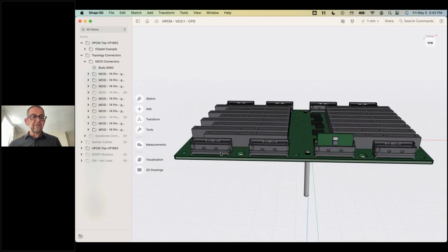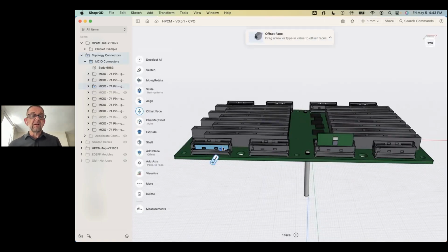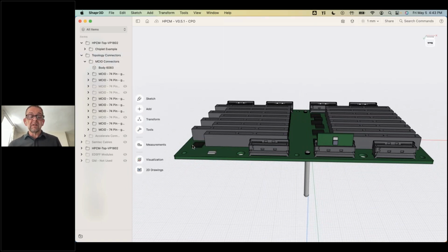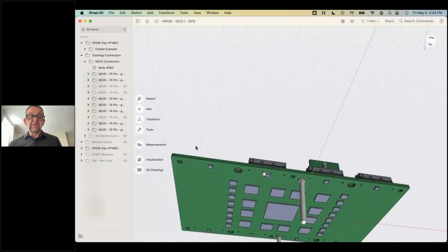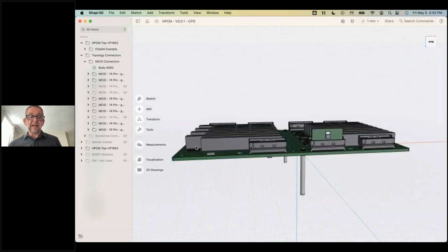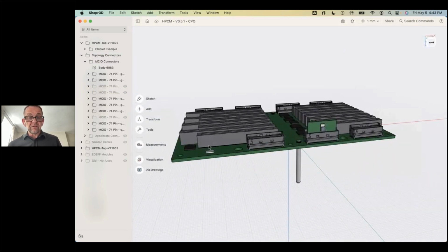So that's that. If I just peel these off a moment, let me just hide that one. Here you can see, so I've just put the optical chip on the back side, and so there would be an alignment issue, right? So how do you get the alignment? When you're stuffing these optical modules, you might need to go through some sort of active optical alignment, so when you plug in the connector, you get a proper optical alignment.